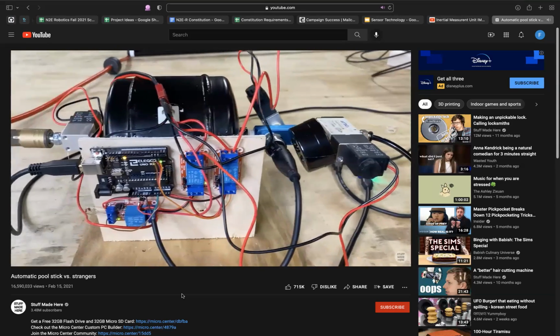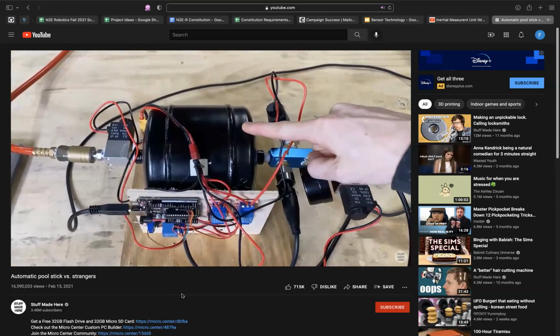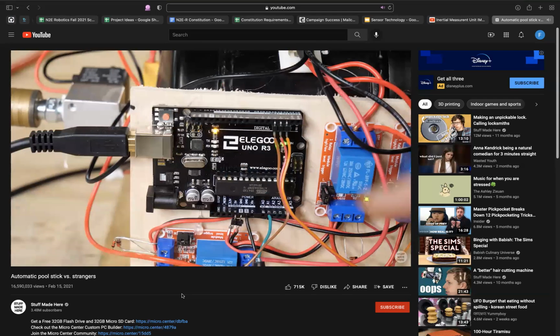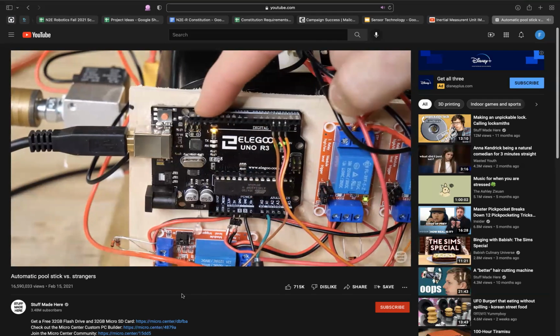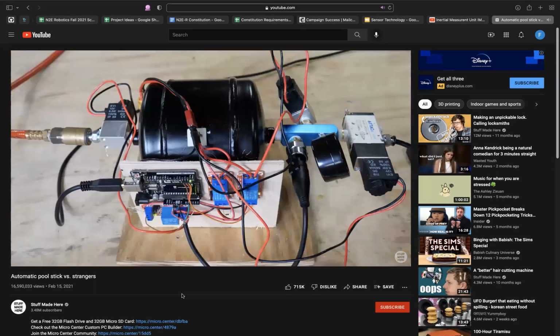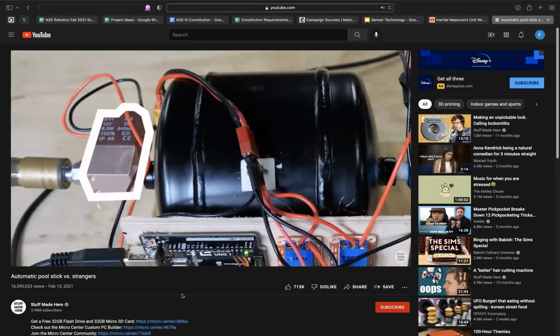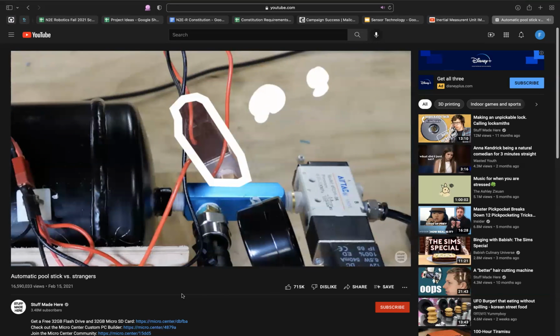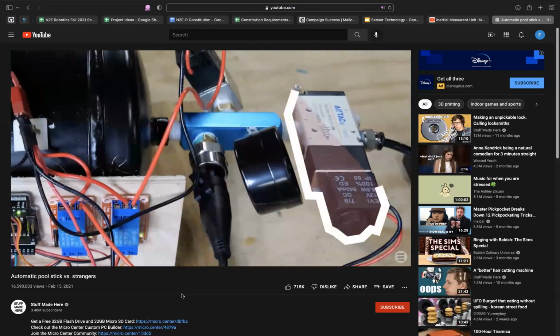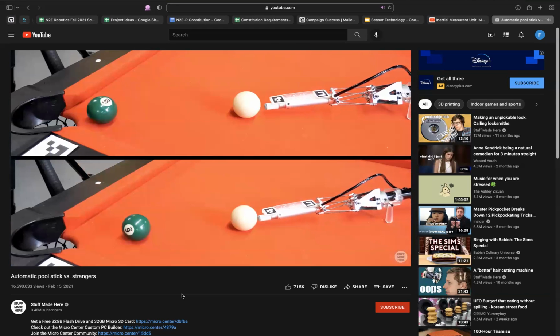To do this, I built the power pack. This tank is normally intended for car horns. The tank has a small, wimpy computer attached to it, which people call a microcontroller. The microcontroller measures the pressure with this pressure gauge. If the pressure is too low, it'll open this valve, which will connect it to my shop air and pressurize the tank. If it's too high, it'll open this valve and release the pressure. And to fire, I open this valve. It's really simple and works well.